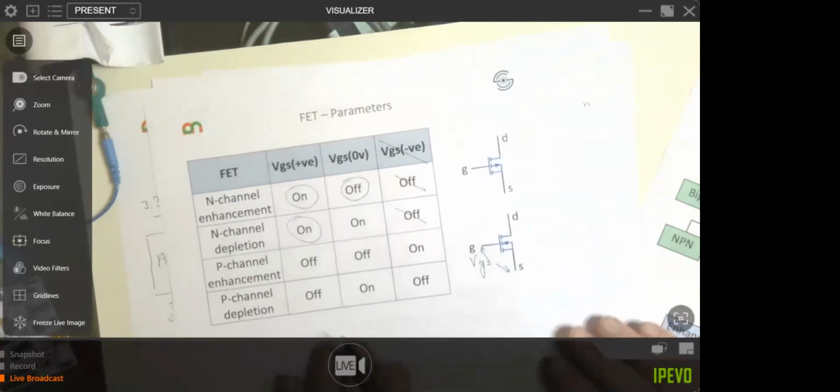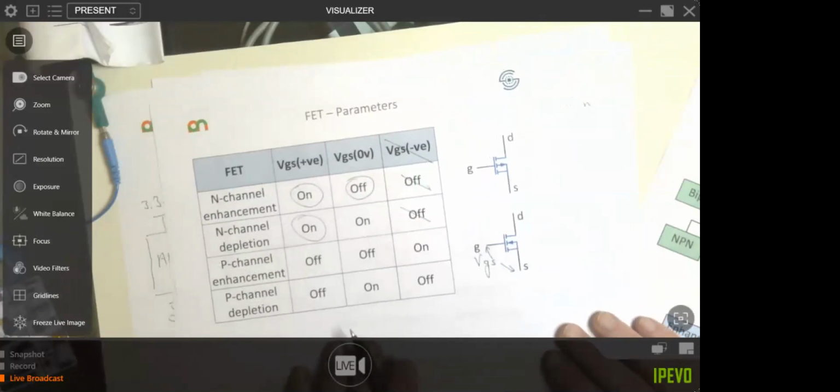So you can see very quickly which one of those I'm going to want, can't you? I'm definitely going to want an N-channel enhancement type FET. And then you essentially go to Farnell or RS or any of the other distributors, or look in the drawer, DigiKey at MakeSpace. There's a load of components. If you're ever in there, at the electronics bench, I think on the left-hand side, there's a rack on the wall. At least there used to be last time I was there. You could have a look in there and you could probably find some transistors that would do the job.